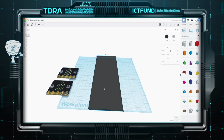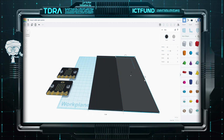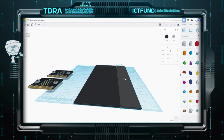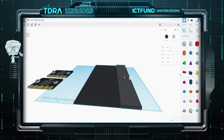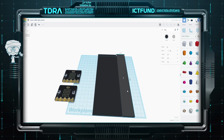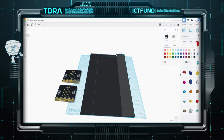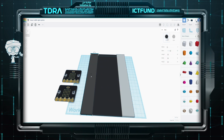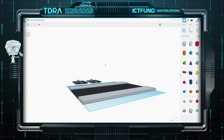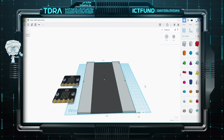And then I'm gonna hold Alt and Shift so I can make a copy of this to the side. Make it smaller, around 30 mm, and add the height as a sidewalk. So this is 2 mm and this is 4 mm. I'm gonna Alt Shift, copy the other one to the other direction. I'm gonna change the color to gray. So this is our main street now. I'm gonna have an empty space down here to hide our microbit later on.